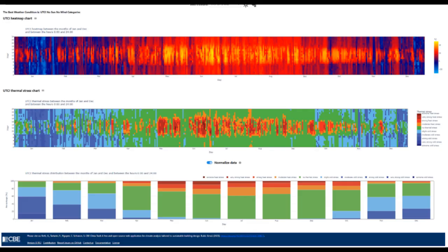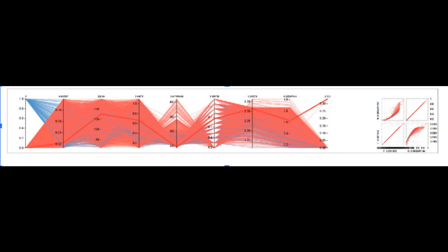We then evaluated three objectives simultaneously. The first is energy use intensity, or EUI. Then thermal comfort, measured using Fanger's PMV equation, and material and operational costs. Thermal comfort was constrained to follow ASHRAE standards, keeping PMV between negative 0.5 and positive 0.5. We also aligned heating and cooling thresholds with standards from Passive House Institute US, or PHI-US, which sets annual energy demand and airtightness guidelines for high-performance buildings.